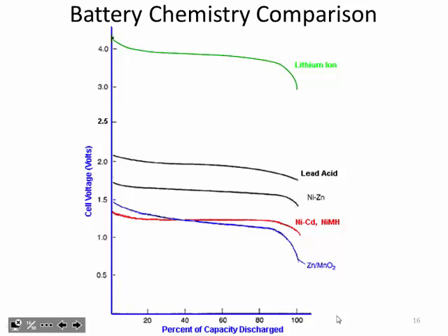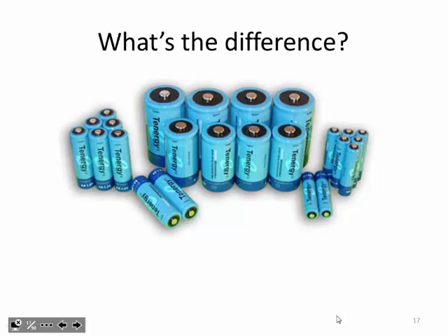You can see the nominal voltage is about 1.5 volts, a little bit higher than 1.5. When these come fresh off, they're about 1.65 volts each. But you can see when you start losing your charge, you reach a spot where you sort of drop off. And when you put a load on over here, it pulls it down to zero, which I had you guys doing. Put a load on over here, it's going to pull you way down. So what's the difference? You know the difference now.